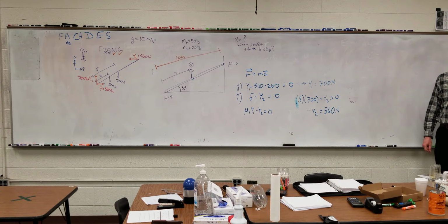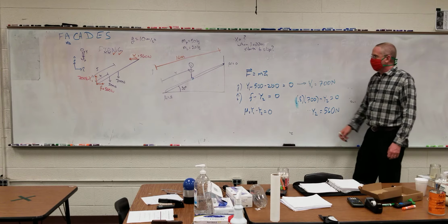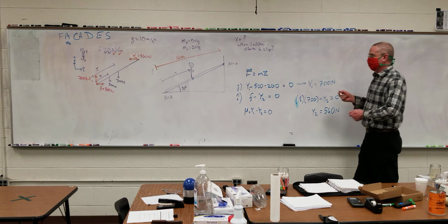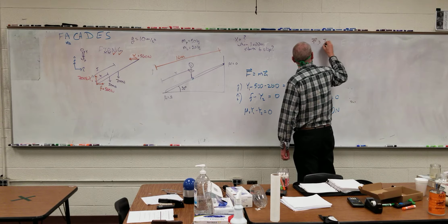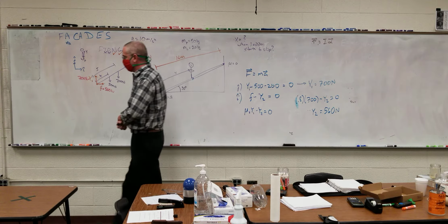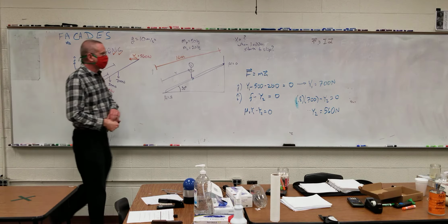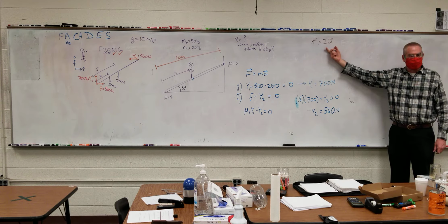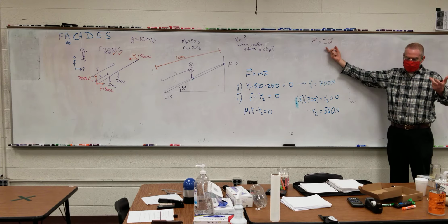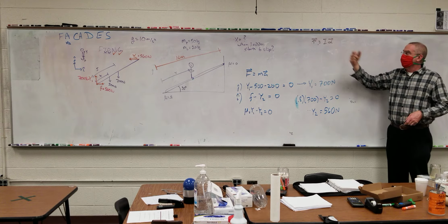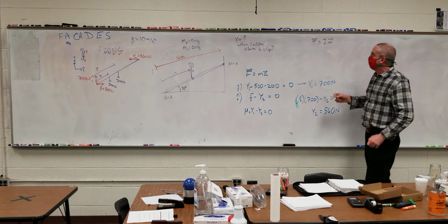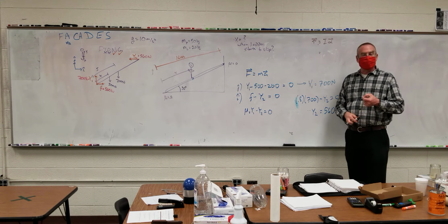We have one more equation of motion that we need to deal with. Now, F equals ma is the classic linear equation that we're dealing with, but of course, we're dealing with rotational motion. So, torque is equal to I alpha. That is the other equation of motion that is necessary to solve this problem. Well, I know what the right-hand side's going to be. It should be 0, right? It should be 0 because the thing's not rotating. There is no angular acceleration, it's static equilibrium in all senses of the word. Similar to the lab that you did 2 days ago.